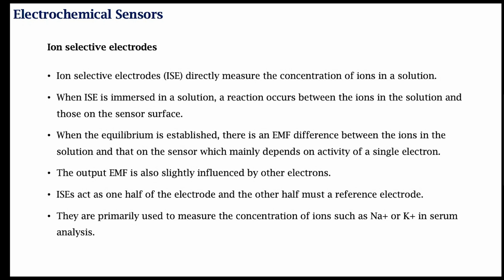The other approach is to use a method by which we measure a current: we apply a fixed bias, a fixed potential, and then we measure a current as a function of the concentration of an analyte, for example, using some sort of Faradaic reactions, such as oxidase reactions, biosensors, for example glucose oxidase biosensing systems, Clark oxygen cells.